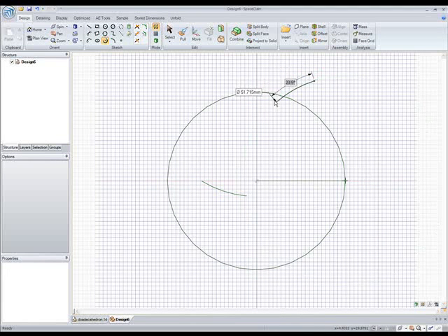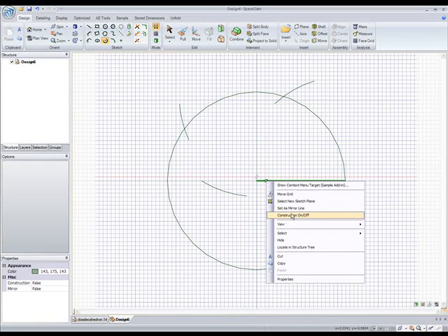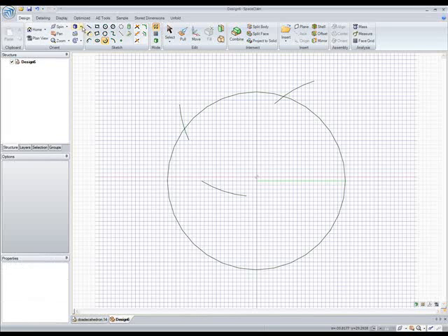You can see we can just snap onto the length that we set up, the radius of that first circle. We'll tick off another one here, and we'll make this line a mirror line just because it'll make things a bit faster. So draw the sides, snapping to those intersection points.